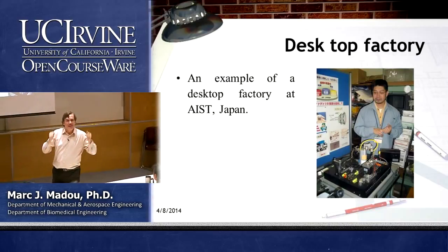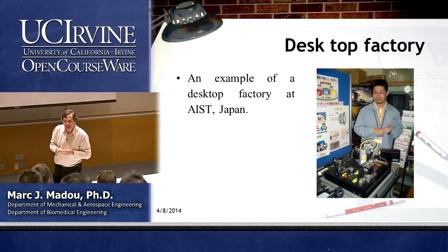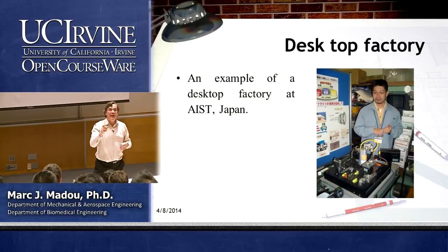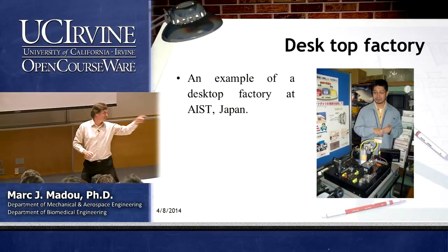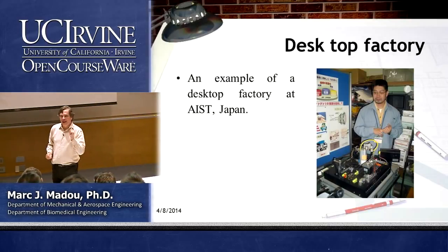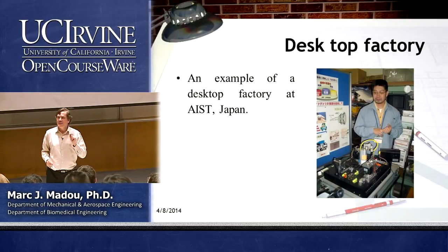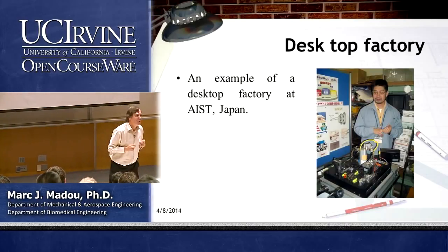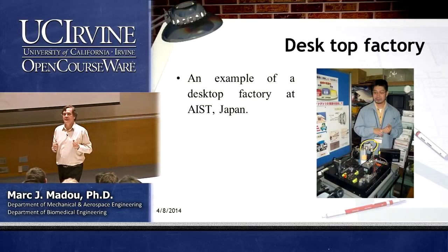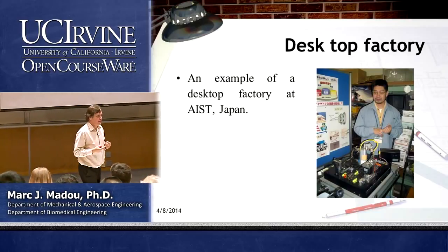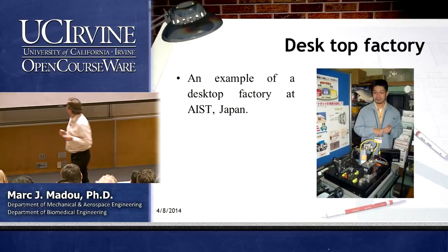Fantastic. You see, the machining there happens because of the matter wavelength. And the de Broglie wavelength of an ion, because it's heavier, is shorter. That is also why if you image something with ions, you can image smaller things with an ion than with an electron, because it's the wavelength feature associated with it that does the job. We'll come back to that, but start thinking already about that. It's not always self-evident. Don't always jump to conclusions.